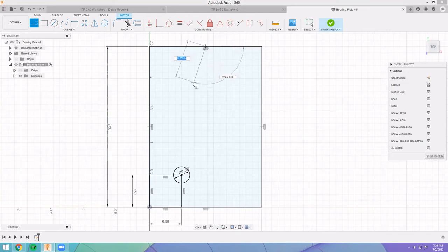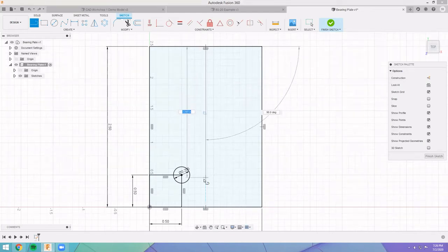That is super useful. So if we wanted to put the other point, we could do the same thing here, like in the exact middle of this line, or we could put it coincident to this bottom corner. But what we really want to do to make a mirror is make this thing nice and straight and intersect the bottom at the exact same point. So if we come down to the bottom here, you can see there's 3 different constraints, which again is good. We've got the X for coincident, the triangle for in the middle. We've also got that little perpendicular icon, the little like right triangle thing.